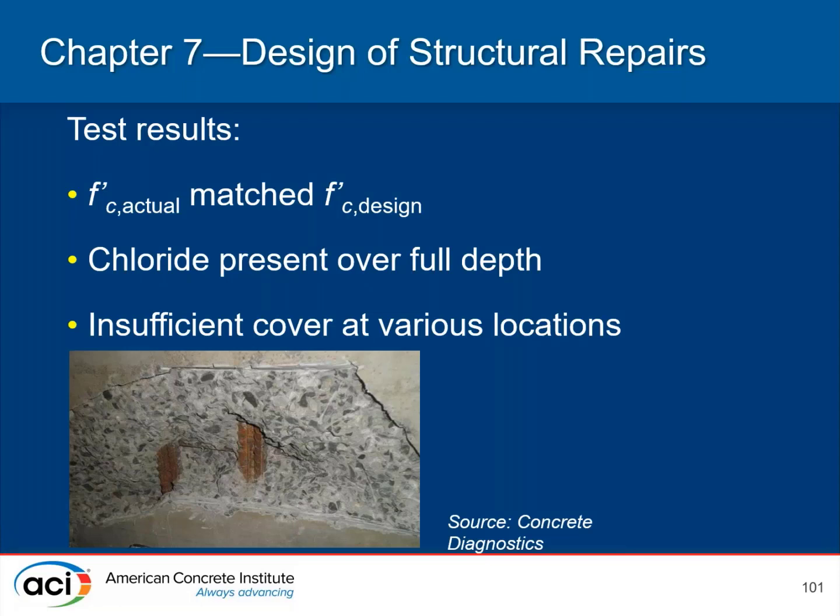So the test results in this case study, as reported, showed that the actual equivalent compressive strength matched that in the design. So there wasn't really any benefit found with respect to what is in place compared to what was designed. Chlorides, as is reported here, were present over the full depth, and there was insufficient cover at various locations. And the source is Concrete Diagnostics here.